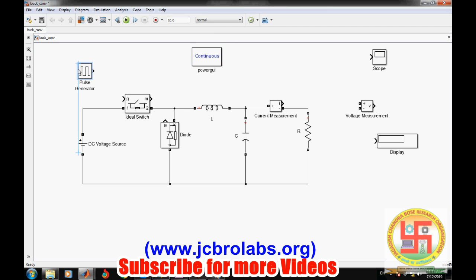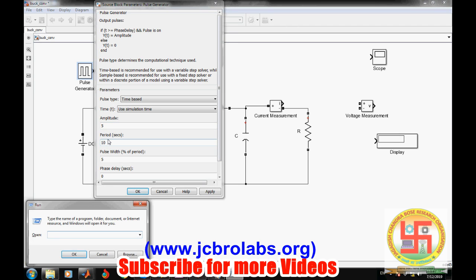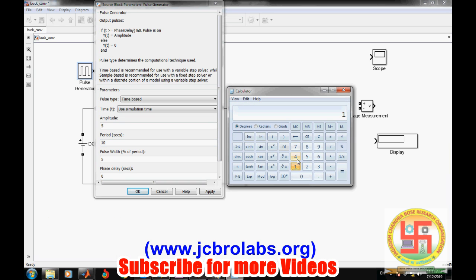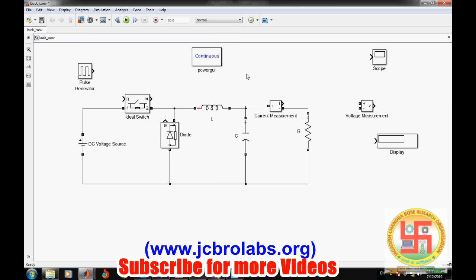Now we'll set the parameters of the pulse generator. So let's say amplitude 5, period. The frequency was 500 kilohertz, so period comes out to be 1 divided by 500 kilohertz. So it is 0.000002. Apply, and then pulse width is 40% duty cycle. Okay, this will connect here.